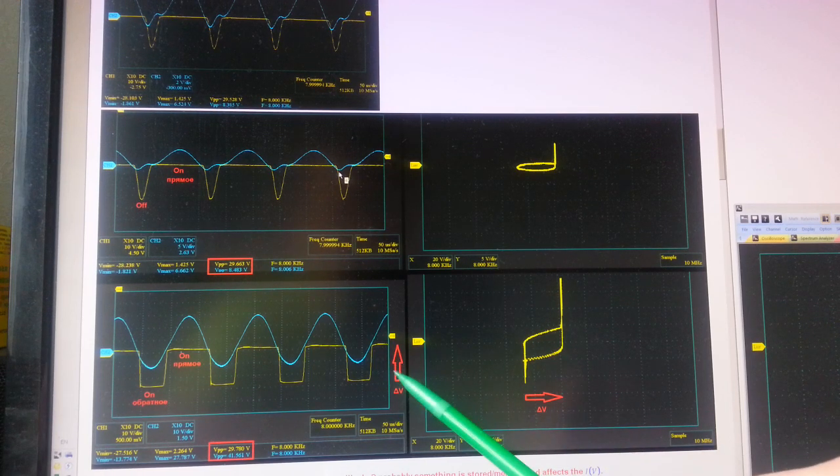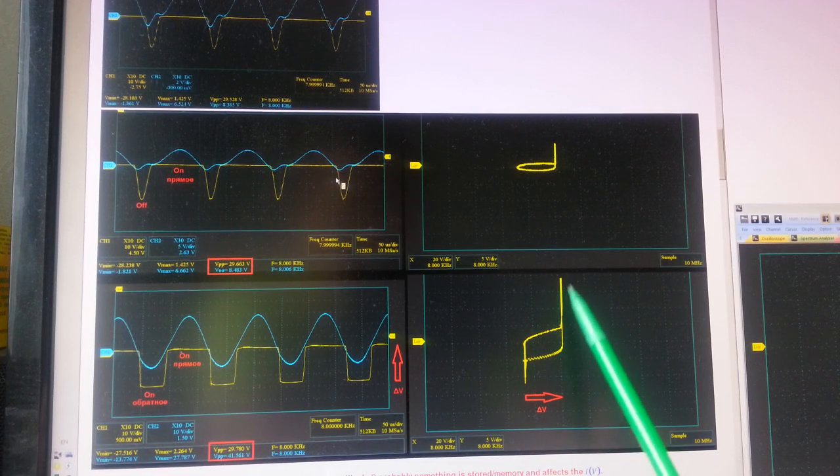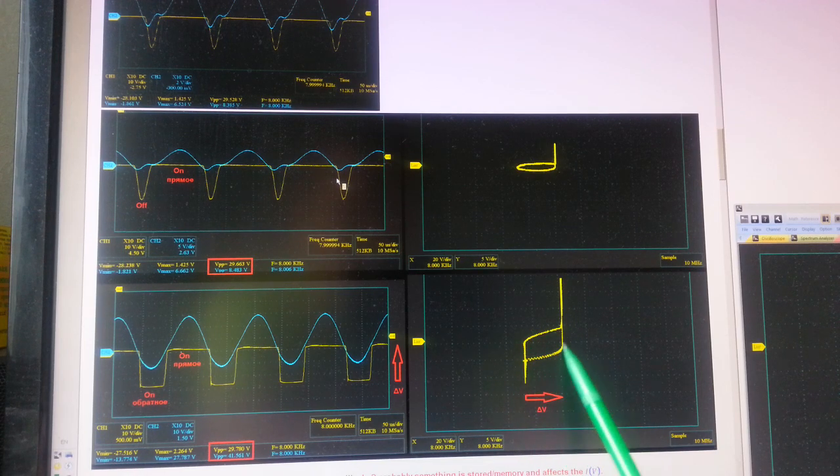So basically the maximum voltage in forward and reverse direction is that, and in this case it's 29 volts, and is defined by the diode type. For Schottky diodes it's a bit smaller. And here is the voltage along this axis. And we have the same kind of size, the same length of this arrow. And we have this nice pattern. Because of the high frequency we have this small hysteresis. So basically it goes like this and then goes back.